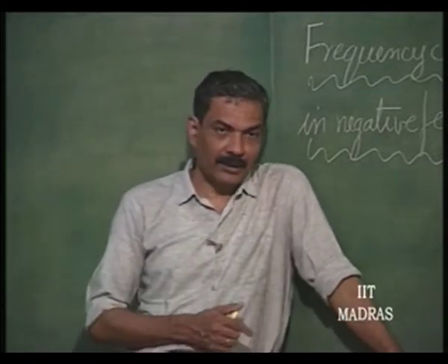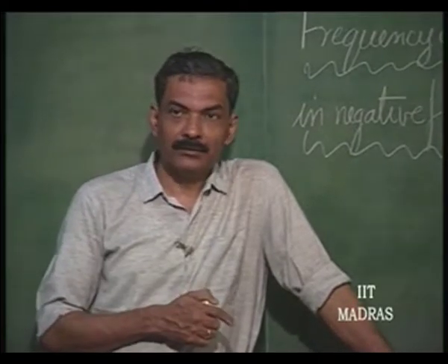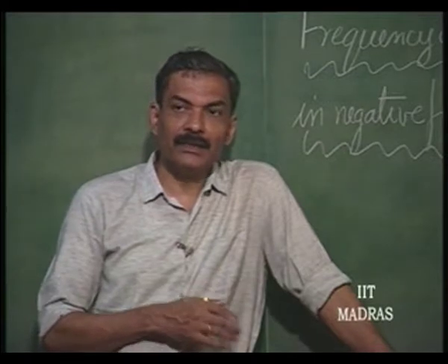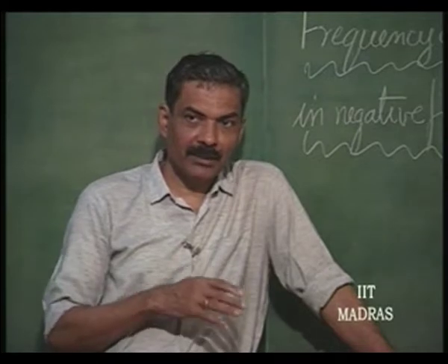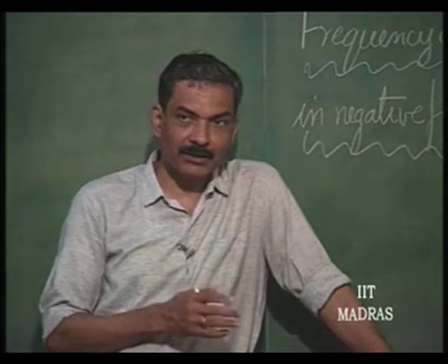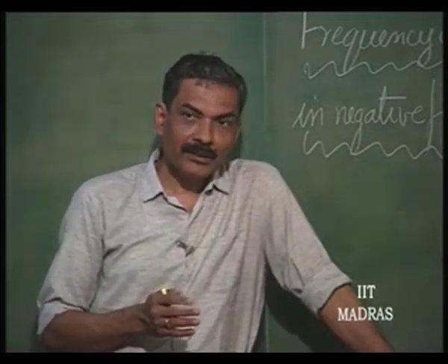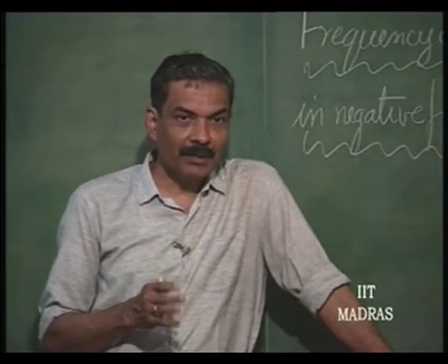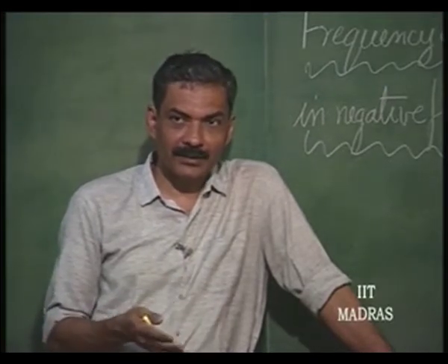Let us understand. We can give negative feedback in order to make the amplifier go towards its ideality. Depending upon the type of control source, it can become a better control source with negative feedback. This is the purpose of negative feedback. Positive feedback should not be attempted, primarily because it will make the gain or transfer parameter more sensitive to active parameters.